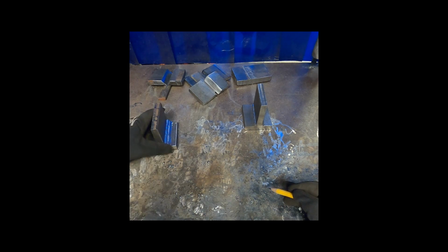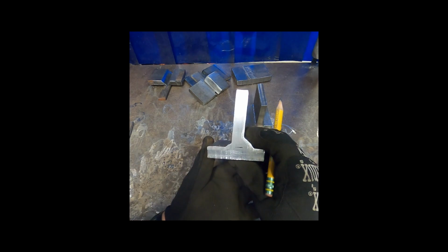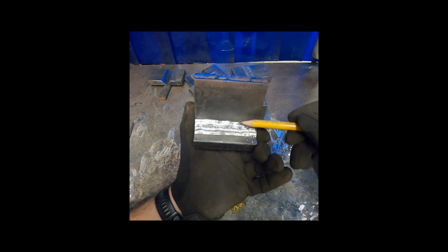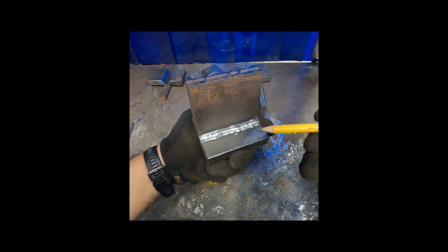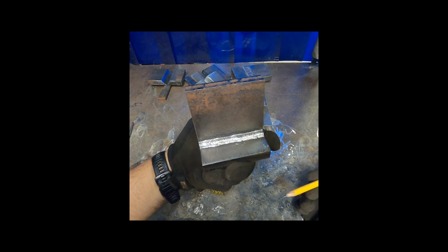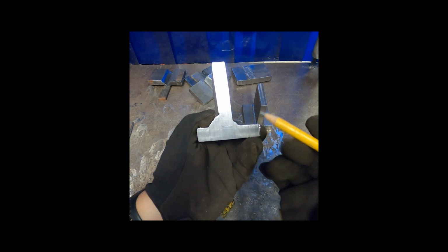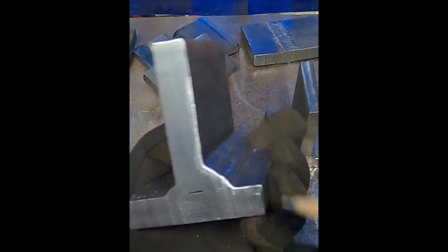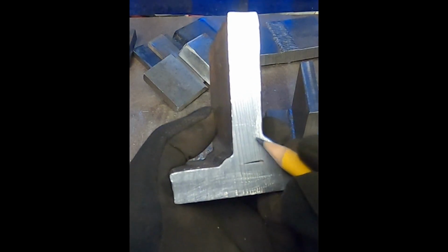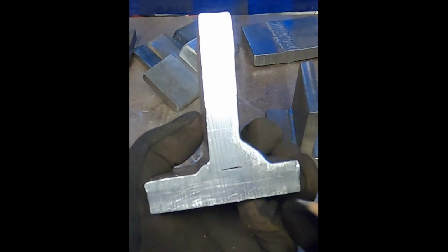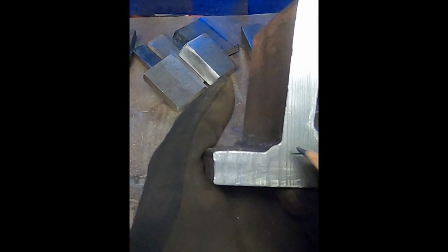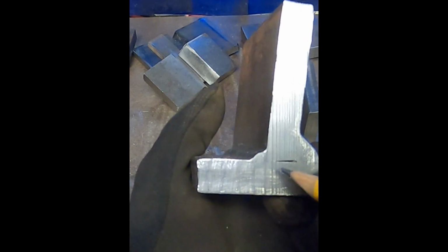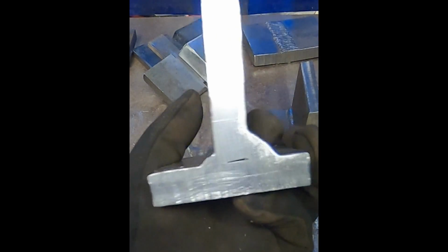And now as I switch over to the second T-joint, you can see one side has multiple passes on it, all of which I did with 7018. And then on the other side, there's just a single pass, same thing, 7018, but I used a slightly higher amperage, I think 145 in this case. And so as we look at it from both sides, you can see that there's an obvious difference in the sizes of the welds. So what I'm talking about, sizes of welds, always remember the length of the legs. So you can see that here.